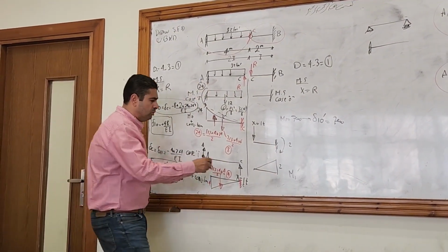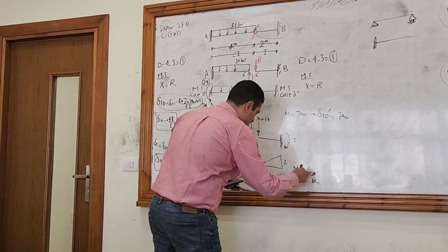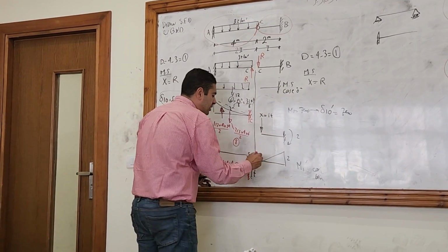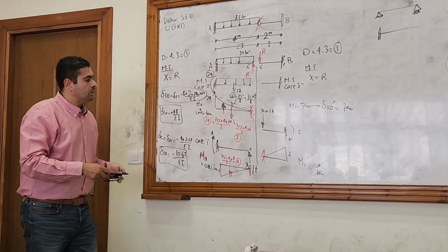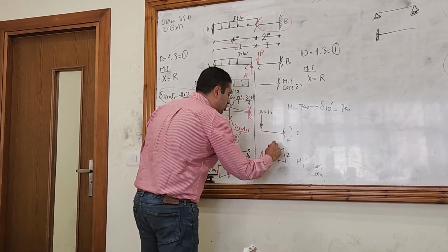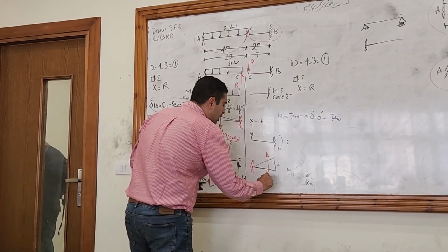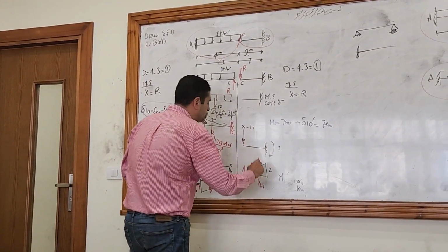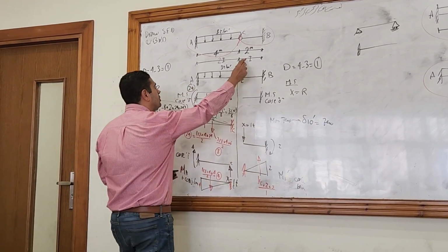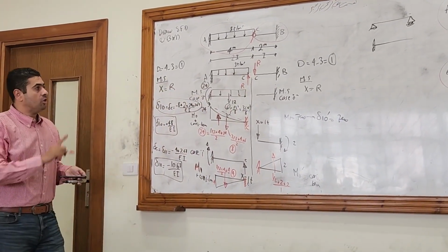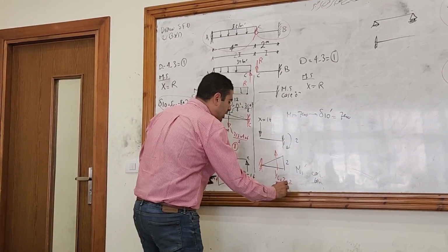Let's put it on a conjugate beam as well. Free will be fixed and fixed will be free. It's only one triangle upwards, above the datum, so it will be upwards. Half base times height, so half the base is 2, the height is 2, divided by the inertia factor, which is here only 1. So it will be equal to 2.